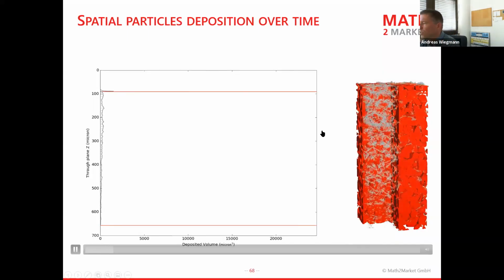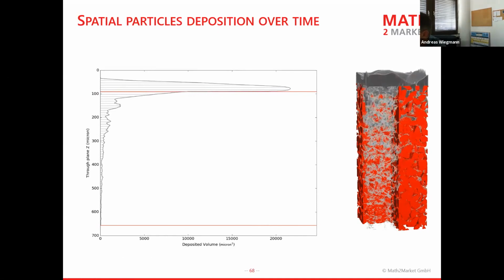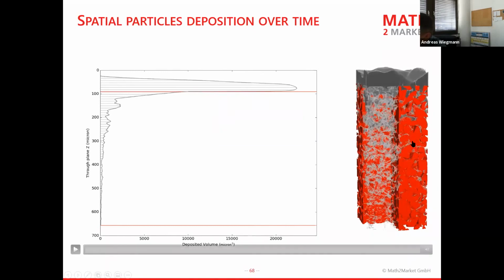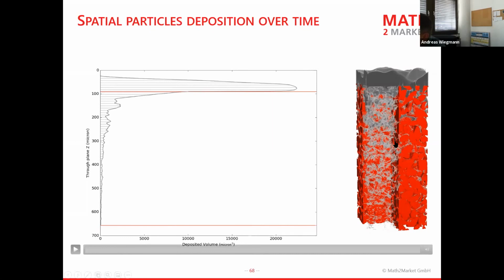So now I think you see that animation again that I showed earlier. So there's the air that moves through this. The first thing is that for a given flow velocity or flow rate, the pressure drop that you are getting out of the air moving through this filter should agree with what you're measuring. Just a clean filter measurement has to work. And when that fits, then you think, wow, I have a good geometry model for the red ceramic grains here, for example. And then, after the structure model and the flow of the fluid through there, we're adding,